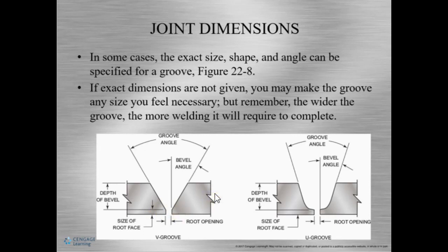Depth of bevel. This can be a little confusing, guys. This is also referred to as size of weld or size of groove. This can show us whether or not the weld will go all the way through the material. In the example shown, the depth of bevel is the same thickness as the plate. If there was not a size noted, then the depth of bevel or groove is considered the size of the material. In other cases, though, the groove or depth of bevel is less than the size of plate.